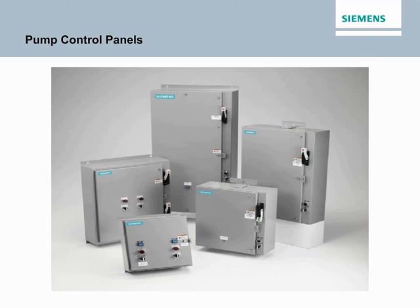Pump controllers monitor flow and/or level variables and control a pump to maintain desired values. Pump control can involve simply turning a pump on or off, or can include more advanced controls for pump speed, output pressure, etc. Siemens pump control panels are factory wired to simplify installation, provide flexible control, and protect against short circuits and overloads. Ample space is provided for field modifications and installation of accessories. Siemens offers Class 87 full voltage and vacuum starters, as well as Class 88 auto transformer starters, part winding starters, and Y-delta starters.